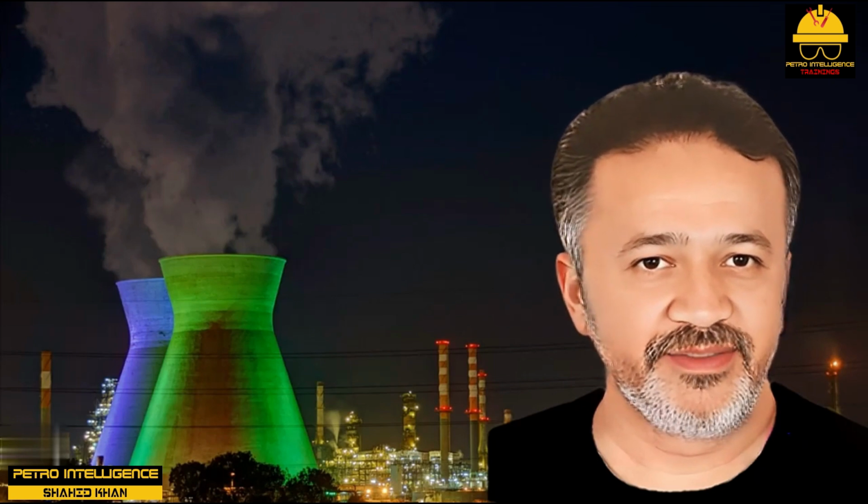It's the mushroom soup story again. Converting the sensible heat content of the water into latent heat of evaporation of the water. But for the air to carry away the evolved water vapor, it has to be below its dew point temperature. To gauge how efficiently a cooling tower is working requires two temperatures. The cooling water supply temperature leaving the basin. The wet bulb temperature of the ambient air.